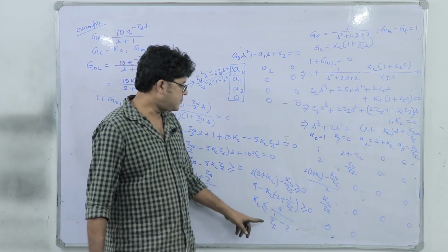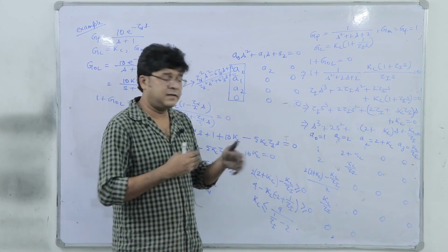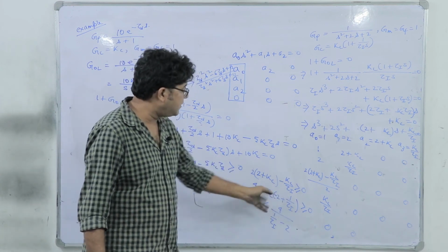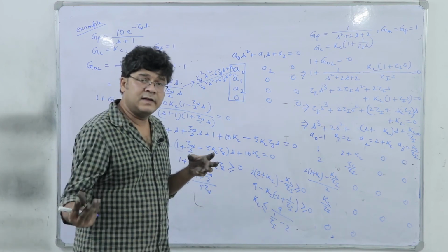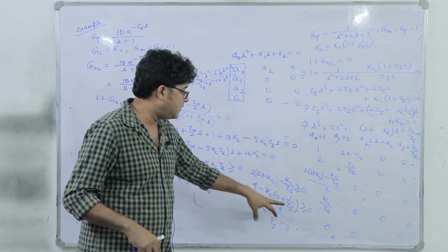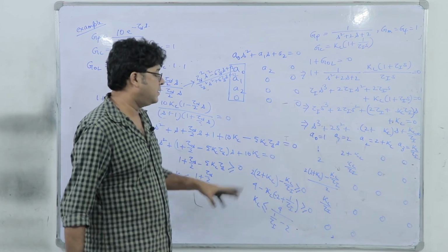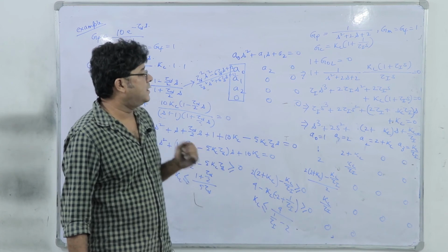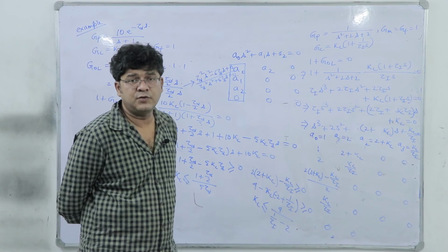Right. This will give you a simple criteria. So if I fix tau I, definitely we will get a range of kc from 0 to this specific value. And alternatively, if I change this expression not for kc but rather for tau I, we can choose any kc, but tau I must satisfy that respective greater than or less than expression of kc. Right. So that's all about the stability, and basically you see the stability will not give you the exact optimum value of this controller parameter.